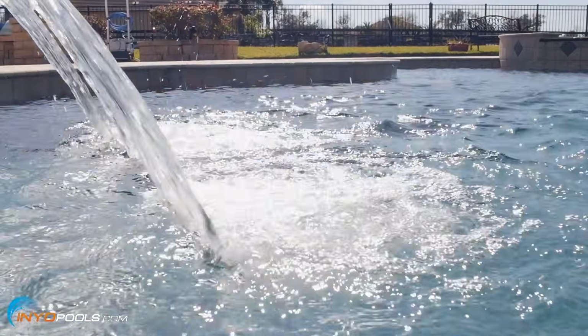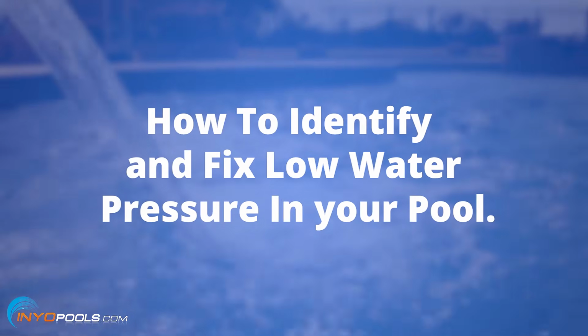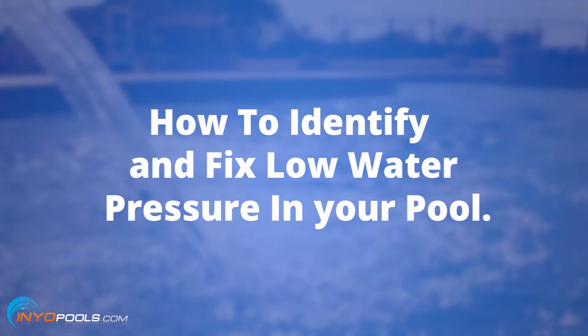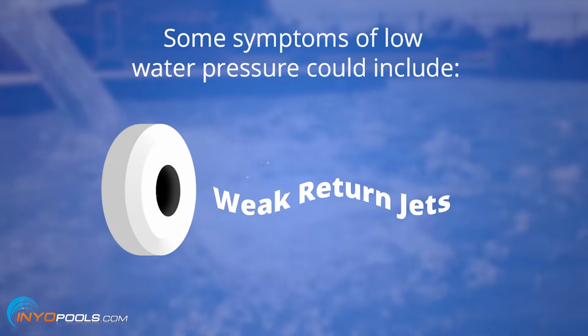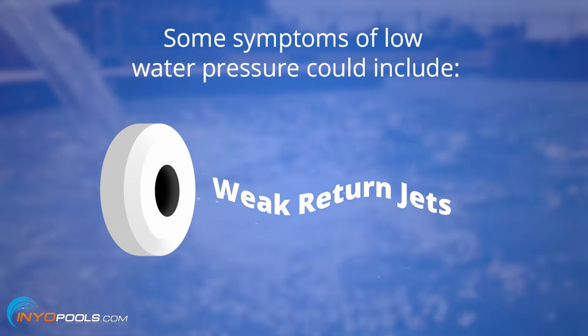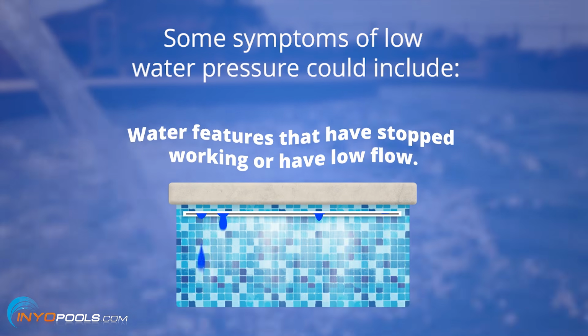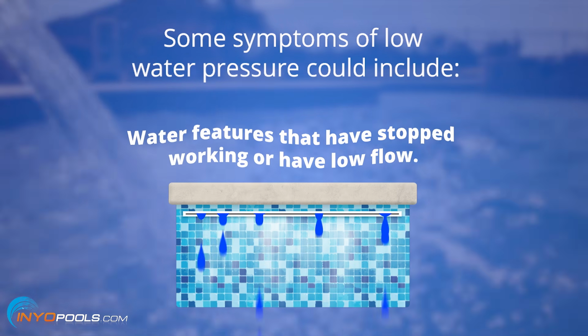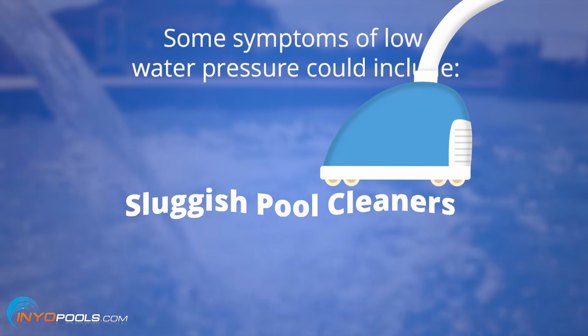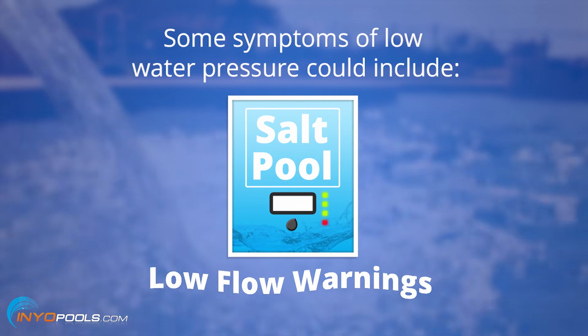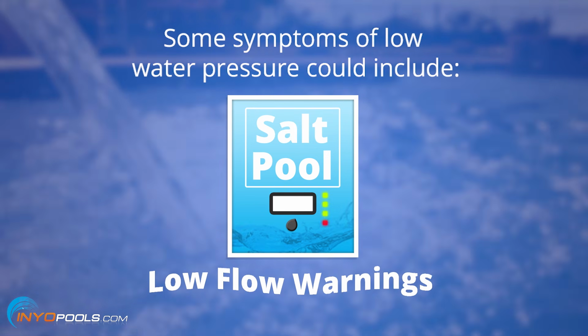Hey pool owners, in this video we're going to show you how to identify and fix low water pressure in your pool. Some symptoms of low water pressure could include weak return jets, water features that have stopped working or have low flow, sluggish pool cleaners, or low flow warnings from salt systems and heaters.